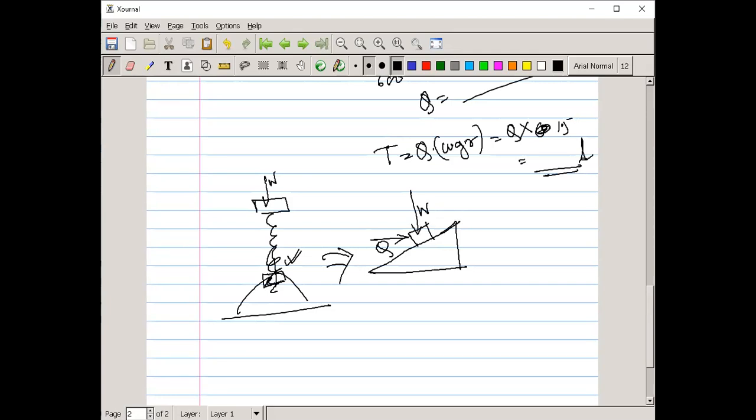And as this is the thread, this was the thread angle theta, I discussed all these things the previous day, that these are the angles with respect to the horizontal axis. So this and the resultant normal, and if this is your friction force, then your resultant is in this direction. And if you want to move your body up the slope, then your normal is this one and friction is on this side.